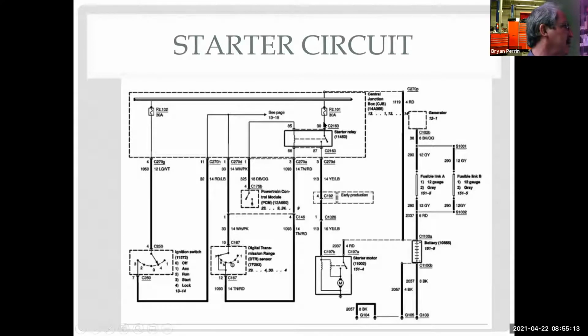So maybe the starter relay is the easiest place to test it at. Because I'd be willing to bet getting to my neutral safety switch or my ignition switch is not the easiest thing to get to. My starter relay, on the other hand, is extremely easy to get to. Much easier than getting to the starter motor itself in many cases. As a matter of fact, some starter motors are buried under intake manifolds. They're 6 hours to get to, so it's not a good test point.